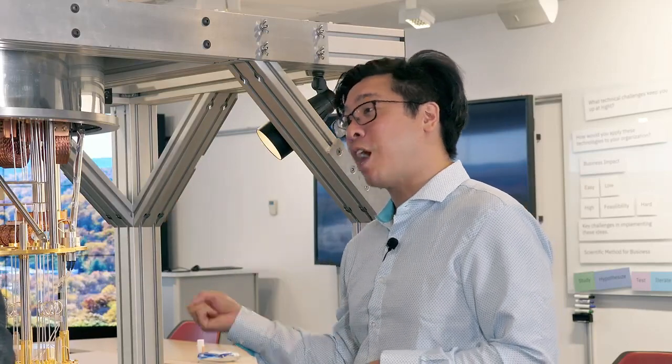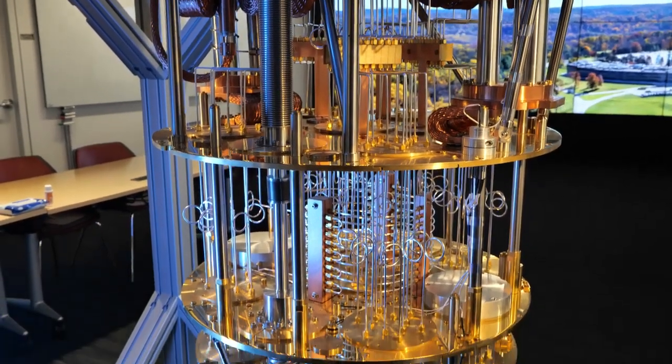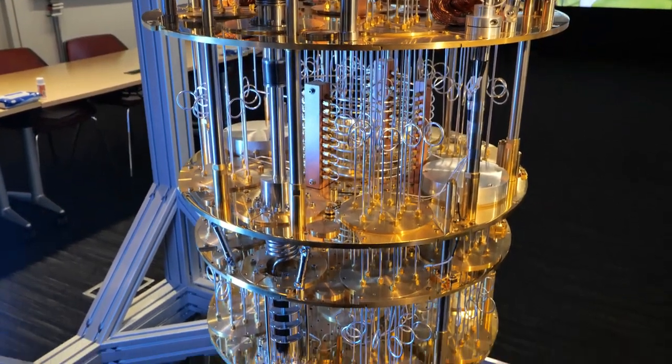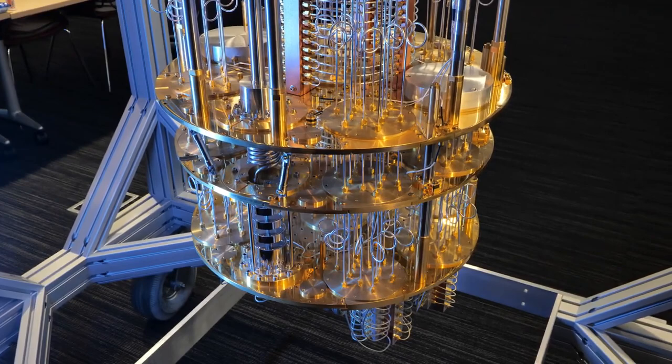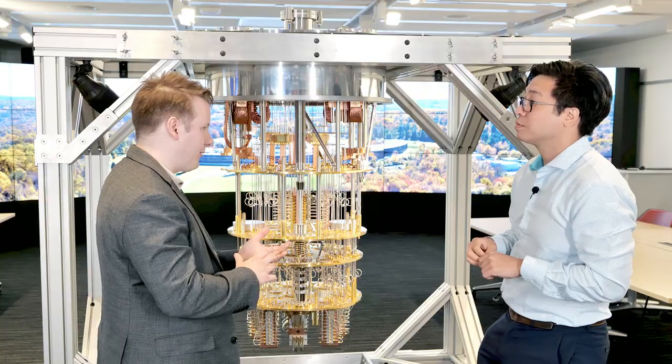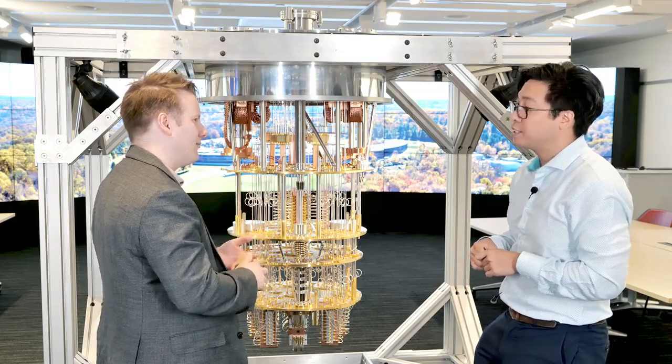So these are bringing the signals, both your inputs and your outputs, to the actual quantum processor. When we program a quantum processor, you're effectively sending microwave pulses from something at room temperature. It's controlled at room temperature, down through these different cables to interact with the qubits that are in the chip. When you say microwave pulses, are we talking about microwave frequency or microwave energy? You got it. Microwave frequencies, pulses of lengths between tens of nanoseconds to hundreds of nanoseconds.